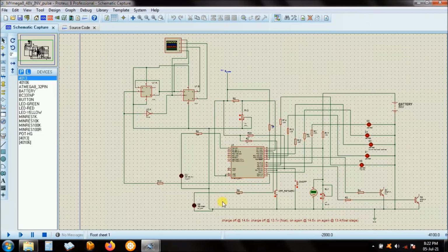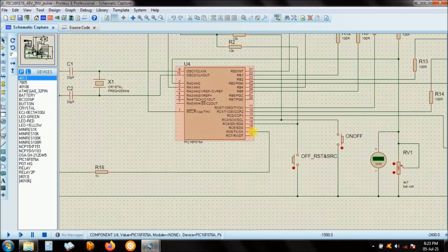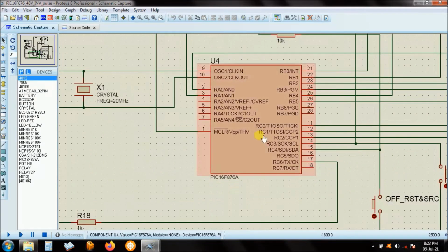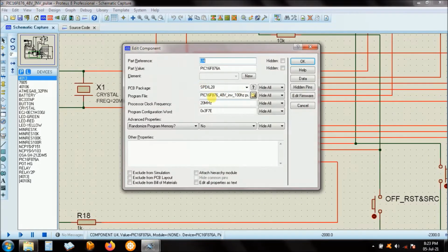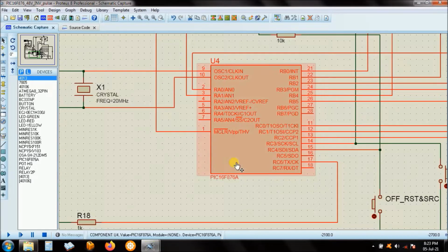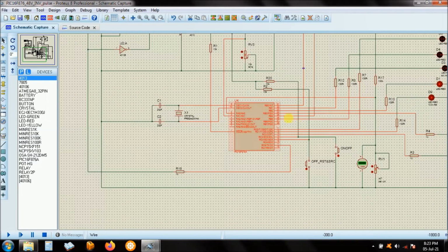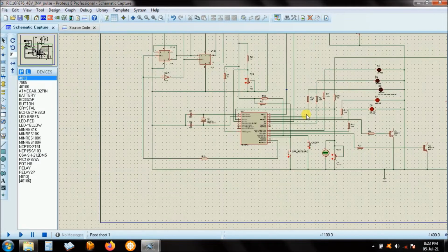Right, so let's use the PIC version, the PIC 16F876A. I'm sure you can take the code that I've used, this one here, and load it to a PIC 16F886, and it will still work, and similar PICs will accept that code. I've done it before on my alarms, where I used a PIC 16F716 with the code of a PIC 16F819. Right, so let's go on.